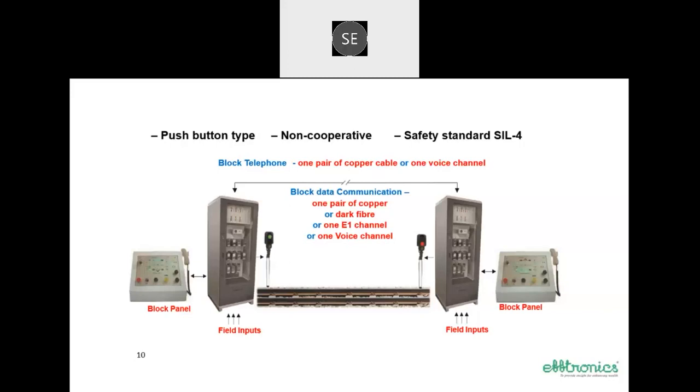Only the motherboard we cannot change from one block instrument to another, because, as I said in the beginning, there is a section ID for each block section. It is a permanent ID for that block section only. So if you receive any other motherboard, we have to change that ID on the motherboard before inserting it into the block instrument. That is the only thing. There is no need of programming, just change the ID, because our purpose is the same and the function is the same everywhere.